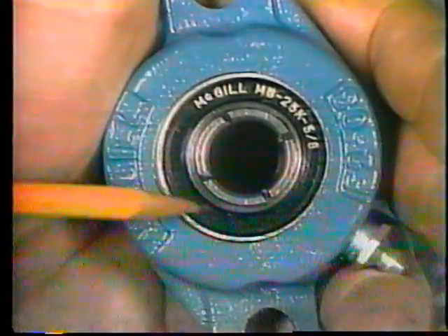Many types of seals will also allow grease to vent if it is added slowly and carefully, but adding it too fast can damage the seal. Labyrinth seals, for example, consist of a series of interlocking grooves or plates which allow grease to squeeze through. Felt seals will push aside under pressure. Rubber or plastic seals like this will also usually allow grease to vent slowly without damage. Be careful though, too much grease pressure can pop them out.